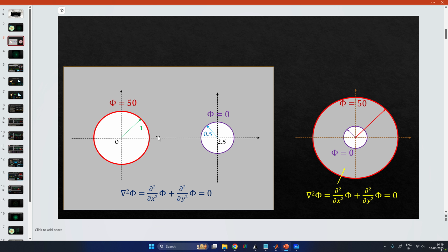So our objective in solving this problem is mainly to do the flux calculation at this boundary. And in finite elements, you must recall the boundary term, which is normal to the boundary, right? That arises naturally from our weak form after integration by parts. So this term is present on the RHS, and we can easily use it to calculate the flux at the boundary. Okay, so this is a very easy process, and you just have to extract the RHS and sum it up, which is called the reaction forces.